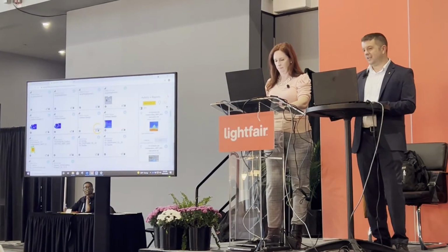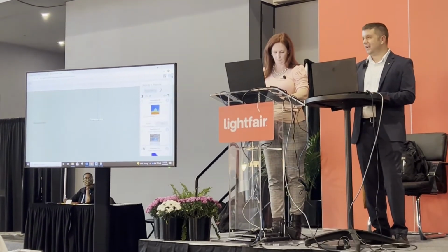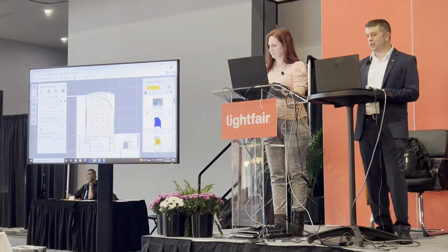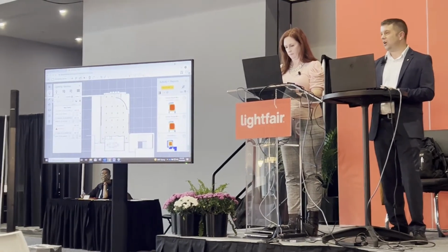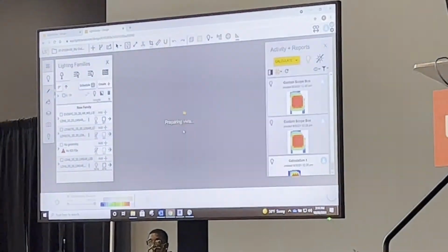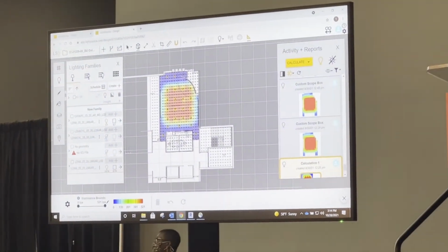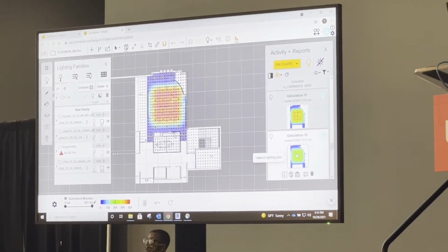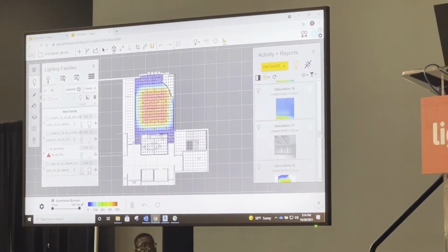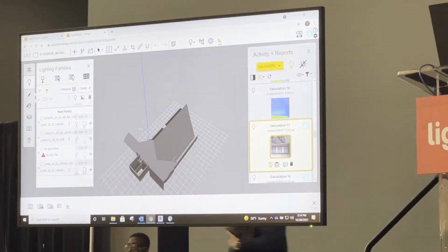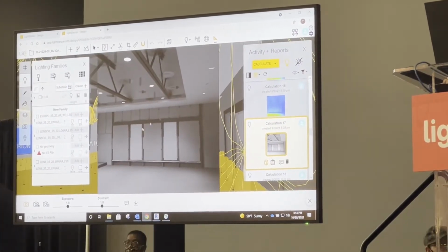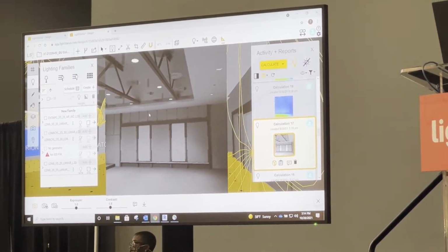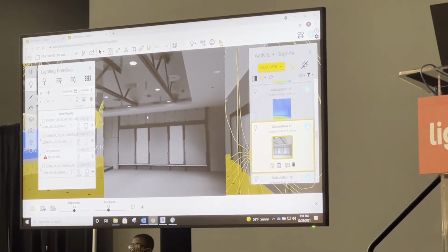And I can click on any of these, go right into it, and as you're calculating things, LightStanza creates this history for you on the right. So I can scroll all the way to the bottom and see my first calculation, and say, oh, okay, he laid some fixtures out, right? Go up through here. Oh, looks like these are a little bit lower. He probably tried some different outputs. Here's some renderings that he ran. Okay, he was looking at this wall. Maybe this wall is important, right? Anyone has access to that and can collaborate and see each other's work that way also.